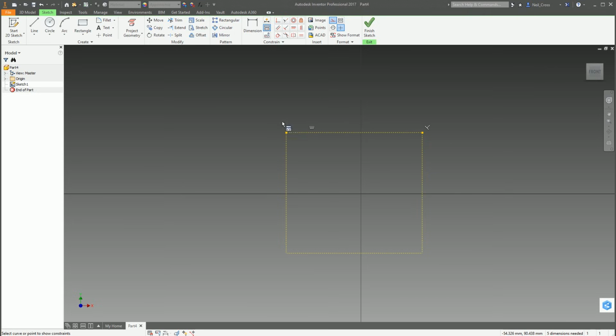So that's select that button there, which is Show Constraints, and then pick the object. You can also use keyboard shortcuts of F9, which turns everything off, and then F8, which just turns everything on, all constraints. It's F9 and F8.